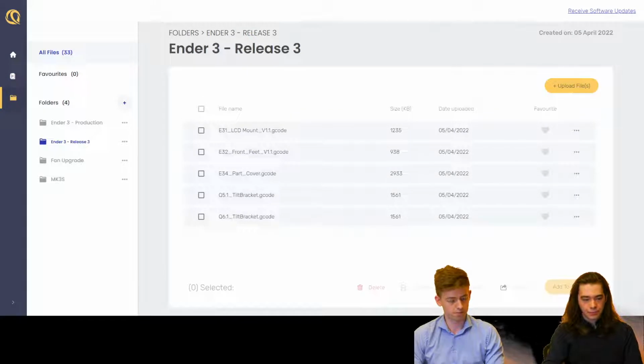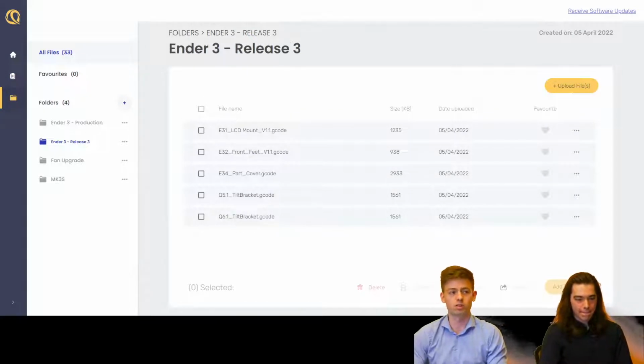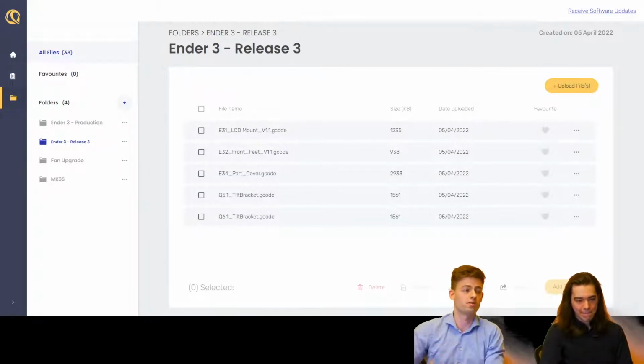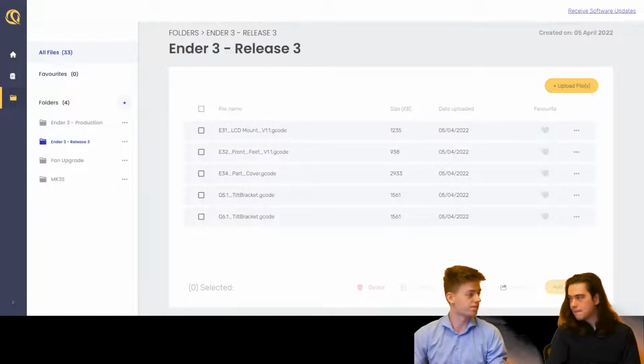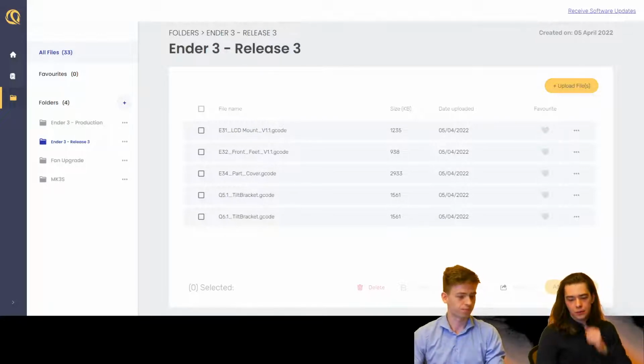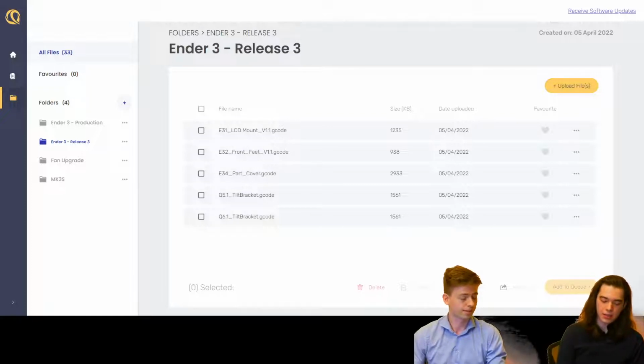So if I have 3 Enders with black filament all loaded, and then some other printers with other filament, I can just say, I want 9 copies of this part, and then each Ender will get three prints assigned to it. Yeah. You can, well, it depends how you set it up. So there's a couple options. One option is to distribute it across the farm. The other option is to send it to a specific machine or specific set of machines.